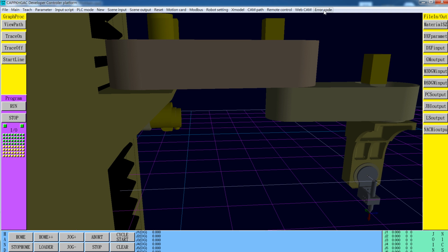The cursor will flash at that line. And then we can press function F9 to set the breakpoint at that program line. You can see in front of the line, at the left side of that line, the very beginning position, a brown circle to show the breakpoint position.